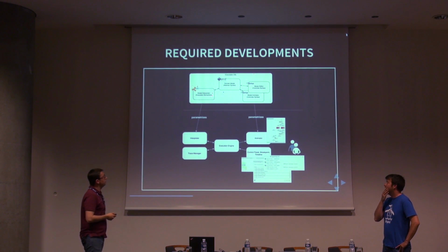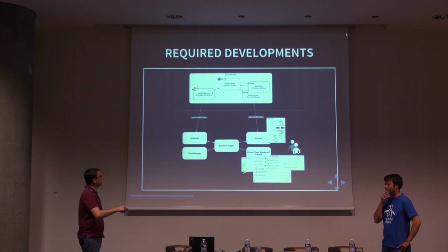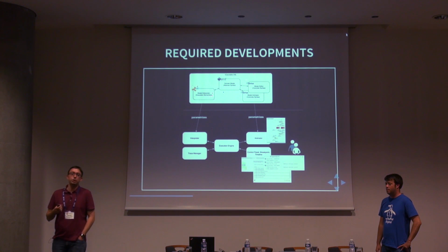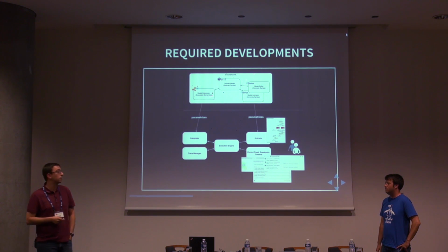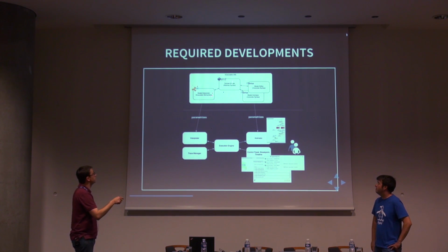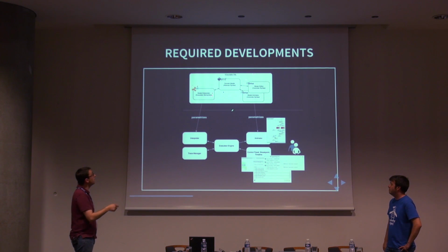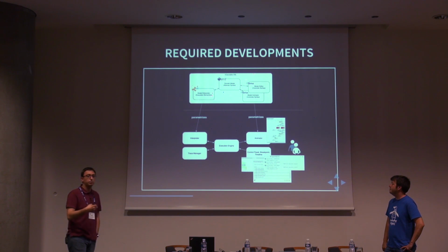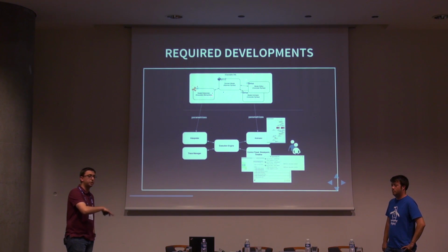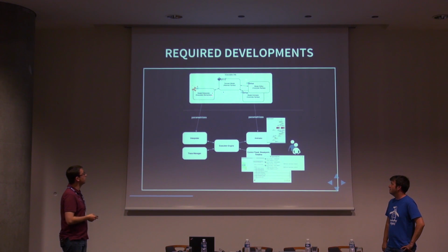The main objective in our work with GEMOC was to provide generic tools for this that are parameterized by the definition of the language that we use for defining the model. The language is defined by a metamodel, the model of the domain, which is defined in our case using Ecore, and we define the graphical editor using Sirius. The first thing that we have to do is to extend the definition of the editor by the graphical representation that we want in the animator. So we extend the representation of the editor by the graphical representation that we want during the execution.